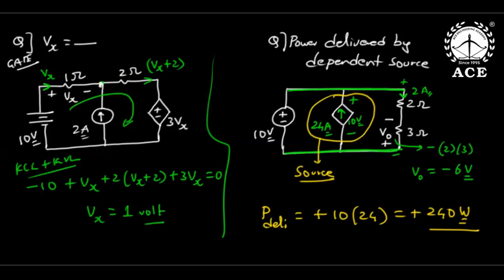So we take it simply. We are satisfying KCL, KVL, but after solving, if it is really dividing, we will get it. Suppose I got Vx negative. If Vx was negative, not positive, then it is understood that this current source is contributing some current to this side. Okay, sir.